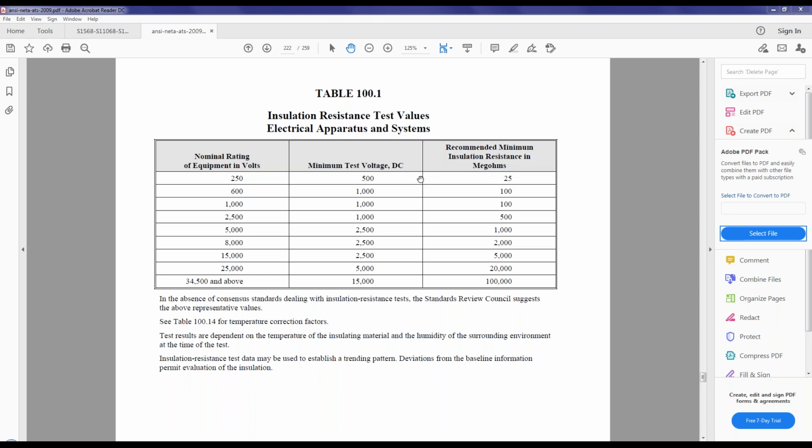Yes, Michael, that's correct. It will depend on the limitation of the test equipment as well. The hipot is much more powerful than the insulation tester. When you do the hipot, you are measuring the leakage current, that's why it displays the leakage current. When you do the insulation testing, you are measuring the resistance, so it will display the resistance value of the insulation. Of course, it will also display the leakage current, but with the limitation of how much power our DC insulation tester can deliver, that will be the limitation for the leakage current measured.